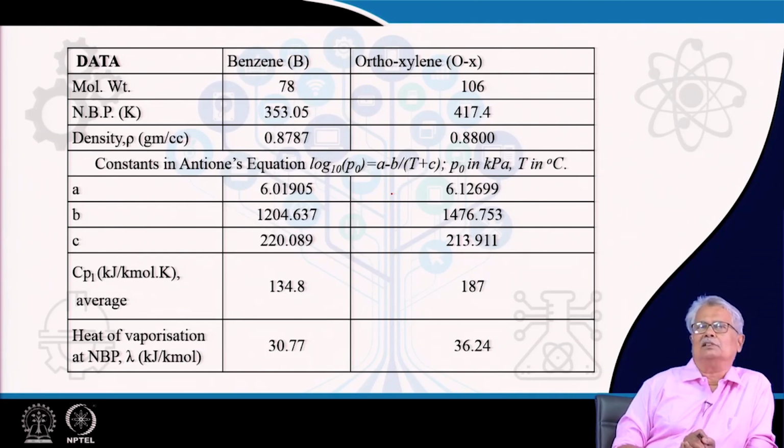In order to calculate the vapor pressure, we are going to use the Antoine equation here. The Antoine equation is typically applicable as long as your prediction remains below 2 atmospheres. And here it is a low pressure system, a pretty volatile system, and in this specific system the Antoine equation is applicable, that we know from the thermodynamic fundamentals. We are not going to go into the details of that.